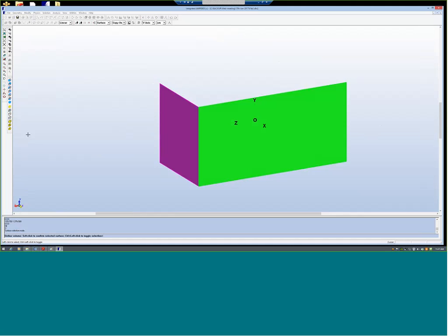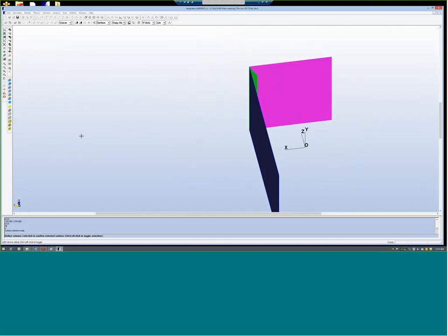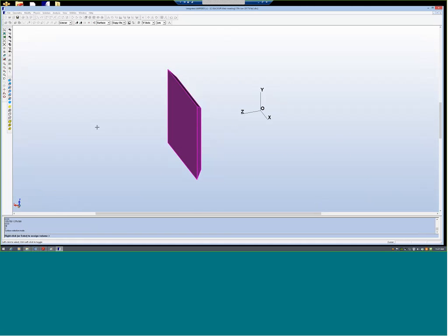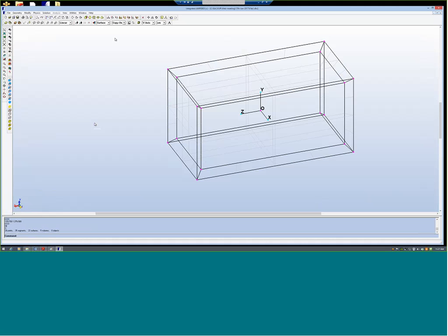So now let's see here. Not the green one, we want the blue one. Control left button. Okay, that's good. Yeah, this is the front wall. This is the wall I want. Okay, done. Next, we will copy on. Take this out. Mirror. Take this wall and mirror 0, 0, 0.